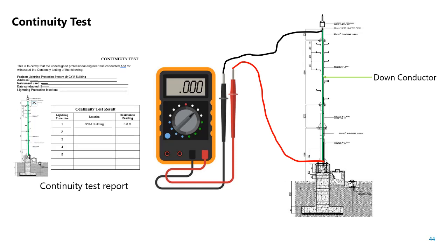The reason is there might be a cut due to the lightning strike, which the cable cannot withstand, and then there is a cut in the middle or a fold which you could not see. So that's why the continuity test is an essential part of the testing. Simple, using a multi-tester, not a special tester.